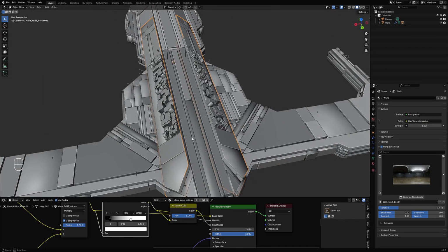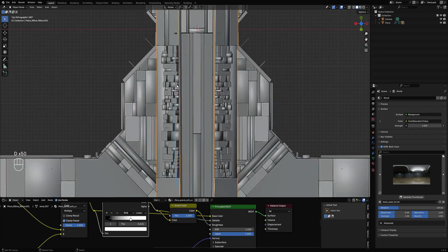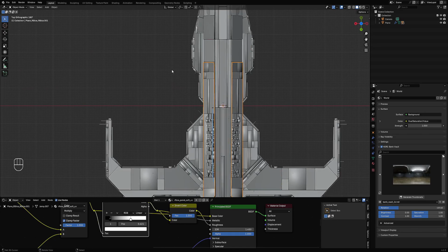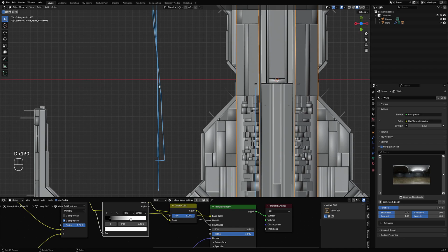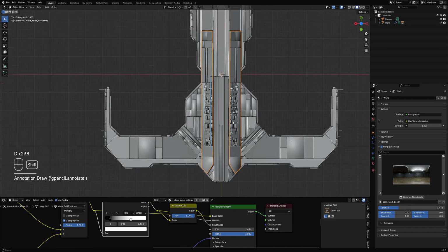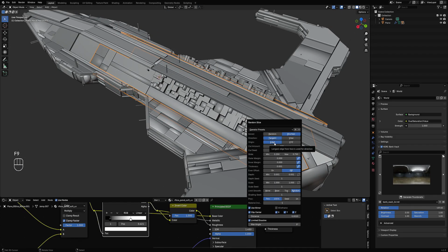Because of the XYZ tangent, it's using the literal YZ direction to create the lines. So sometimes if you have an edge slightly off the literal axis, it's going to create a line there and then create a really small, long thin face, and then create the cuts from there, thereby creating those really thin faces. So just switch over to edge if you're having trouble with the XYZ origin.